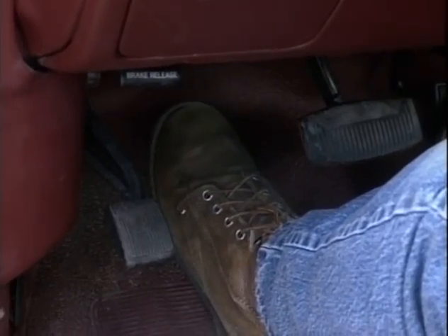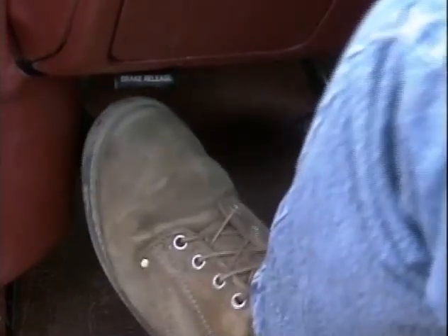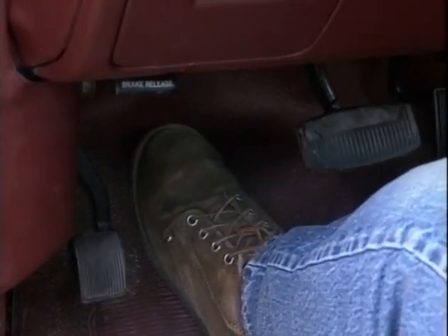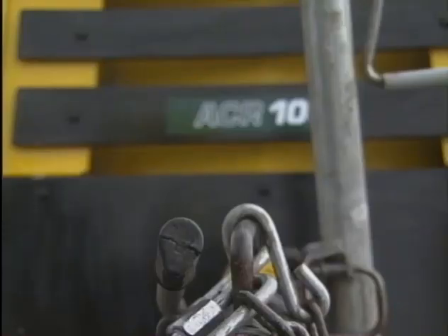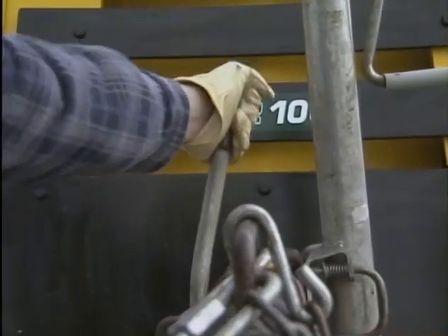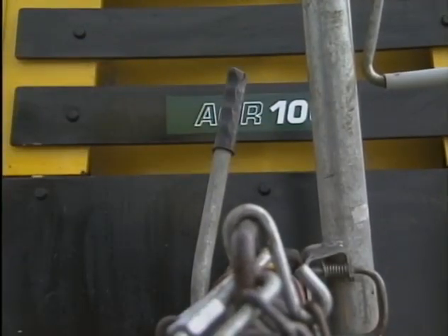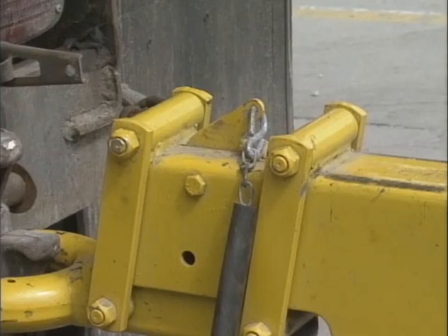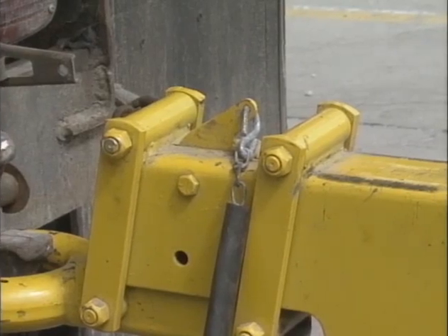Make sure parking brakes in the towing vehicle are set, or that its wheels are chocked or blocked, or that it is otherwise restrained from moving. Then, release the air compressor parking brakes if provided. Make sure the air compressor wheels are not chocked or blocked and that all tie-downs, if any, are free. Test running brake operation, including breakaway switch operation if provided.